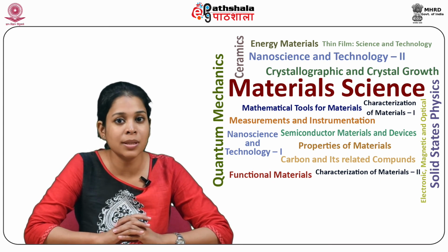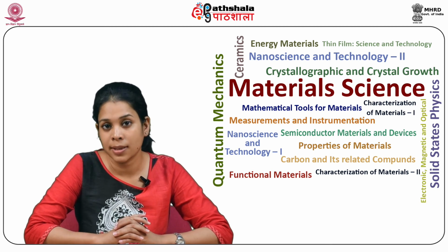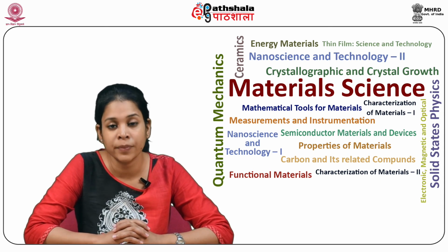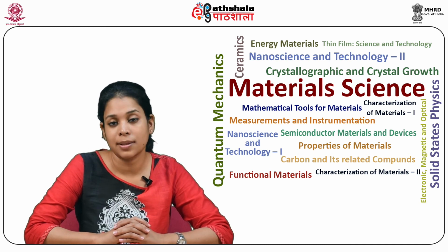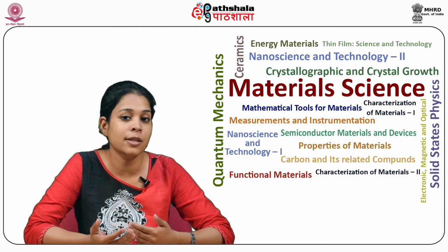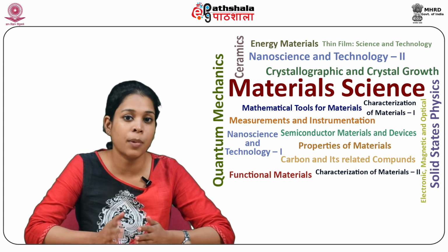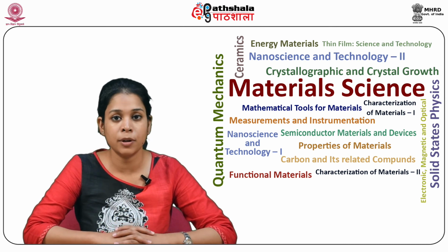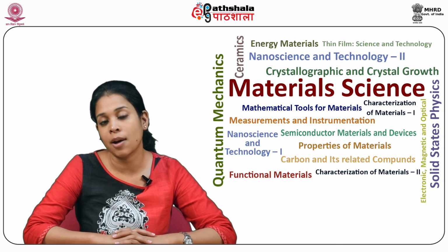The compounds like Y2O3, that is yttrium oxide, next is hafnium oxide, that is HfO2, silicon dioxide SiO2, aluminium oxide, that is Al2O3, are far more insulating and have conductivities in the range of 10 to power minus 5 to 10 to power minus 14 per ohm per centimeter in the temperature range 400 to 1000 Kelvins.